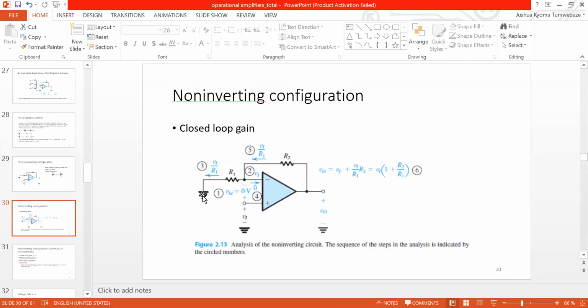Then I also gave you an alternative, and I said that if you want, you can denote your currents in the opposite direction, but of course, you denote them as I1 and I2, okay? And then determine I1 and I2. You'll find that they'll give you a negative value, or you'll have a negative in your expression, implying that the currents actually flow in the opposite direction. So you can do that.